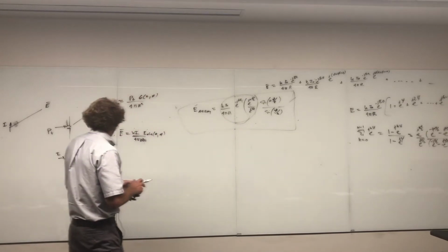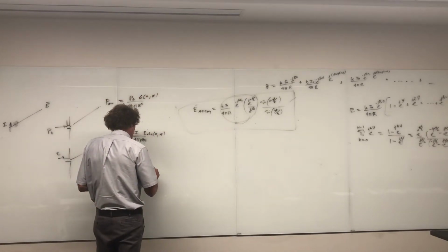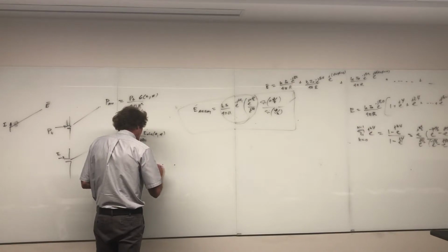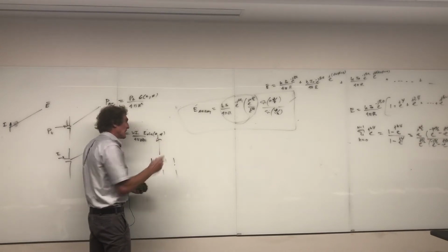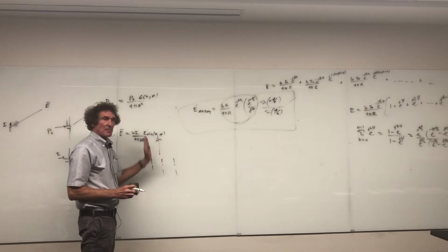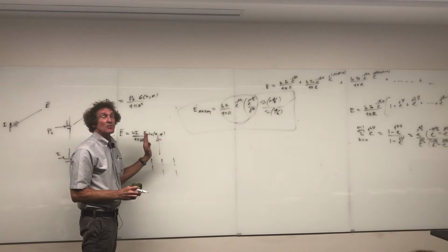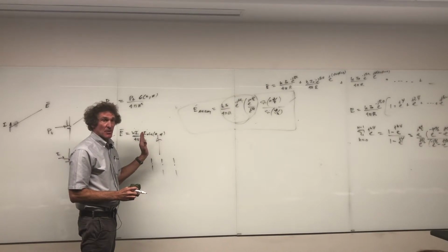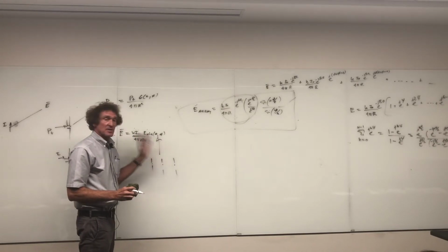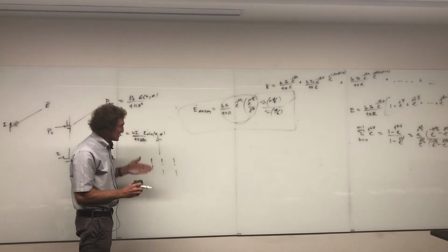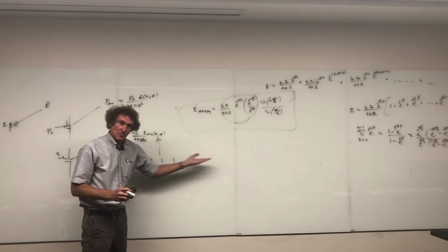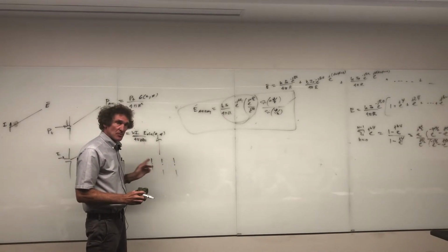In other words, suppose I've only had 3 elements. If they're dipoles like this, in this direction I'll have no power. The dipoles themselves radiate 0 power up and down the axis they're on, and this array doesn't help that any. There's still 0 power. The maximum power will be in this direction, perpendicular to the antenna element's orientation.